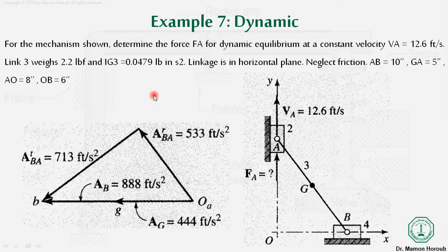We will be using this acceleration polygon. If you remember, when we were solving the example related to the analytical force analysis, we were using the acceleration polygon in order to calculate the inertial forces and the inertial moment. So here we will also use this acceleration polygon in order to calculate the inertial forces and the inertial moment. Okay, so if you can see in this problem, the force Fa is unknown.